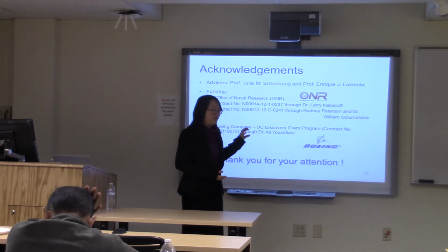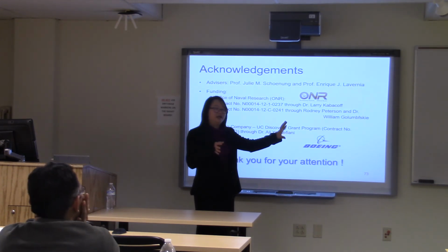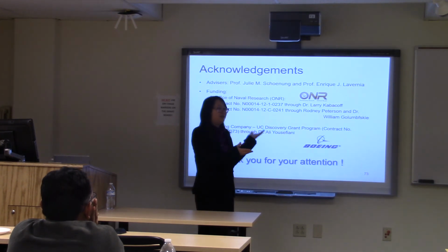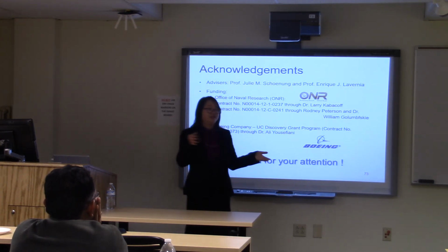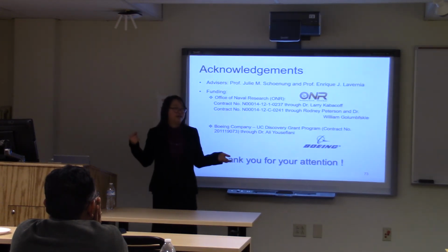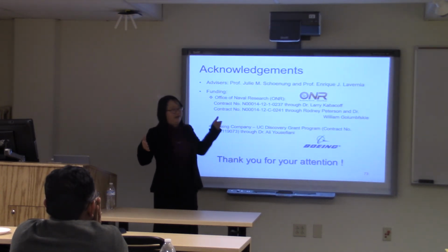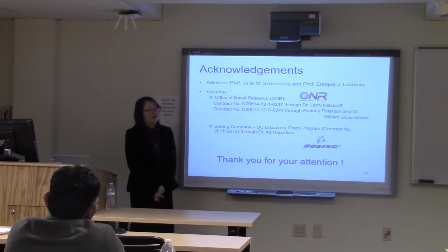because that's actually what I feel about the spraying. At this point, right now, people haven't really created a very perfect CAD profile, but that's also something we can develop as additive manufacturing, 3D printing, if we can combine the computational. It's spray using dynamics instead of melting your material. There is cold spraying right now also. They use very high speed injection of your powder, so the powder is not melted, so you can retain the nanostructure.